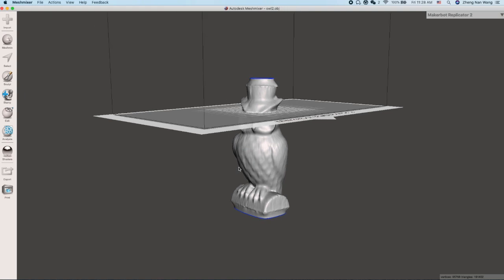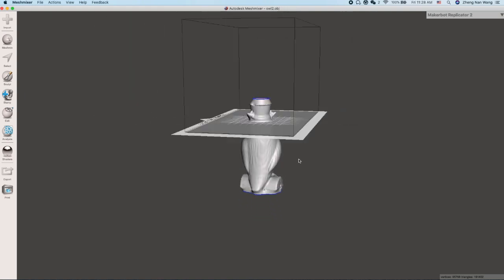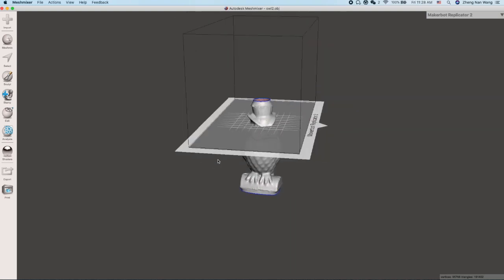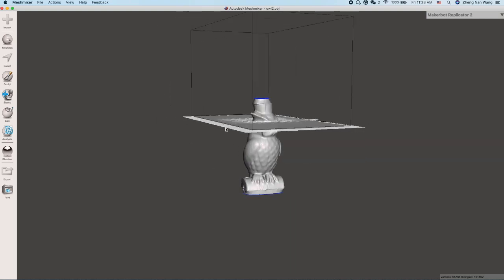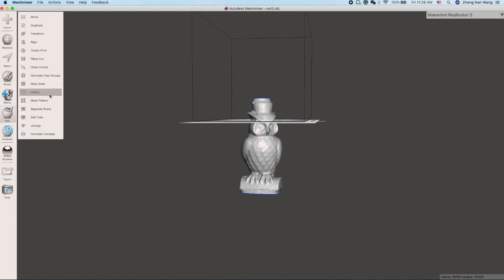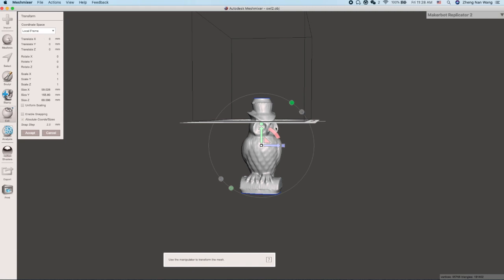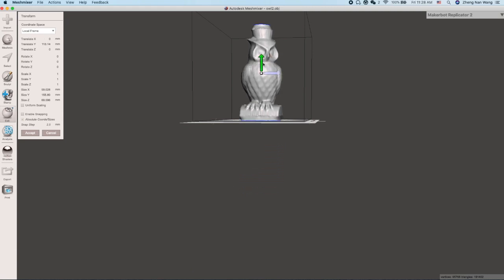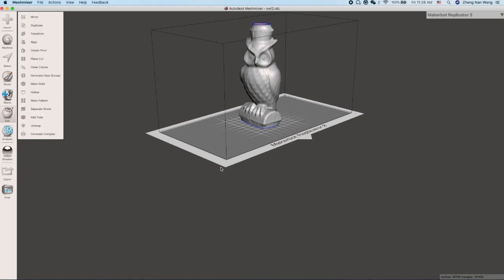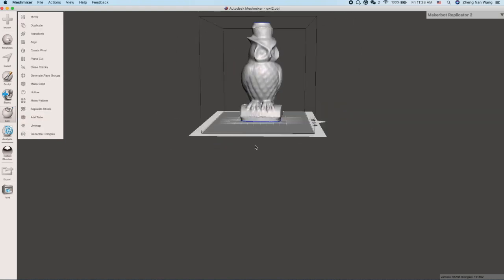All right, so now you get this 3D file you've just exported from MeshLab into MeshMixer. You will notice the placement probably isn't right, and to correct that, you just choose the Edit tab, and then you choose an option called Transform. Okay, so on the Transform, you can just easily move the object around, like so. Okay, once you find a good position, click on Accept, like this.